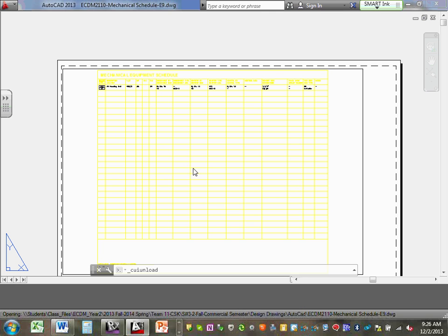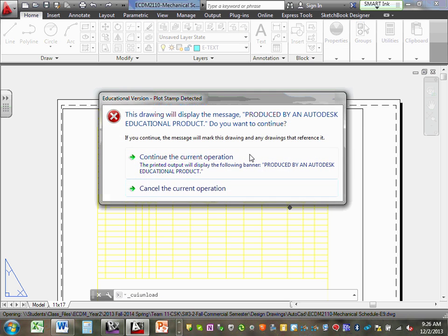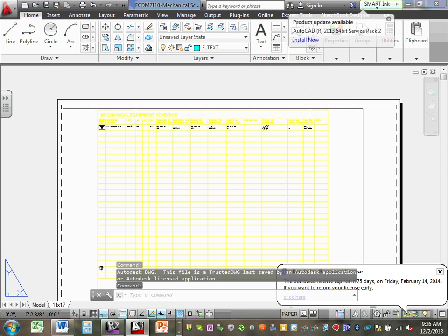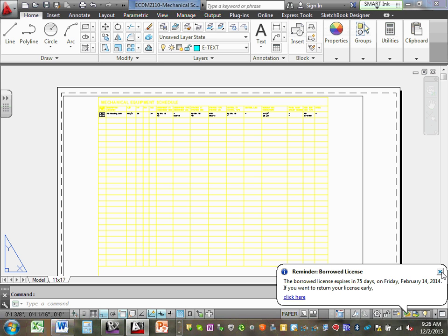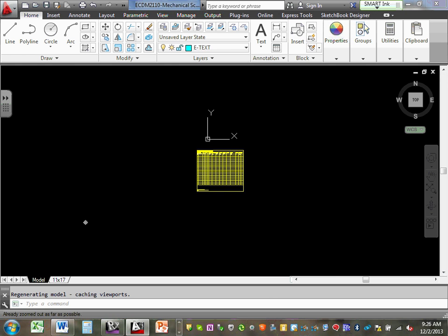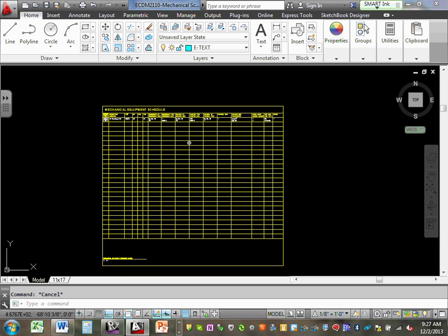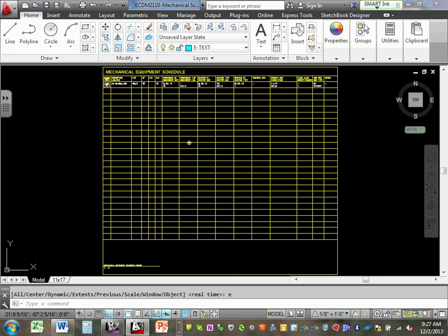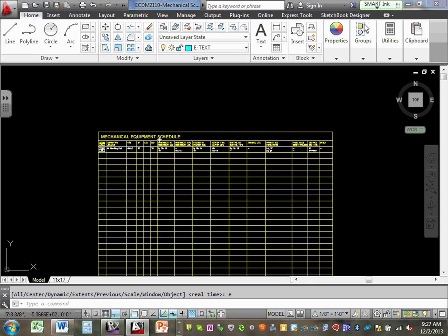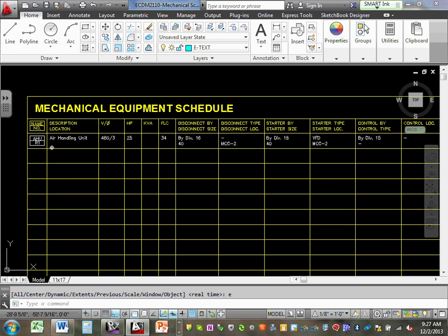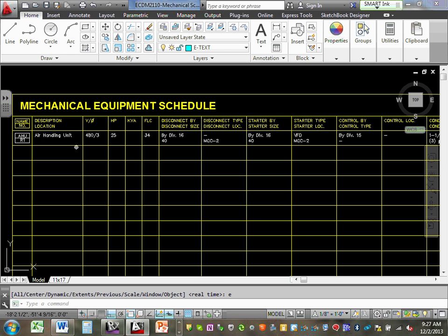Go open this baby. Okay, continue. All right, so grab this one, put it here. Got our license. Go to the model space. Can you guys see that there is a schedule? What layer is that? Schedule lines. Here's the schedule that you have. Everybody can see that? Z enter, E enter, make sure that's the only thing you have there. Cool? Now all these schedules could have been filled from Revit, guys, but let's just fill them here. Everybody got that? Relay schedule?